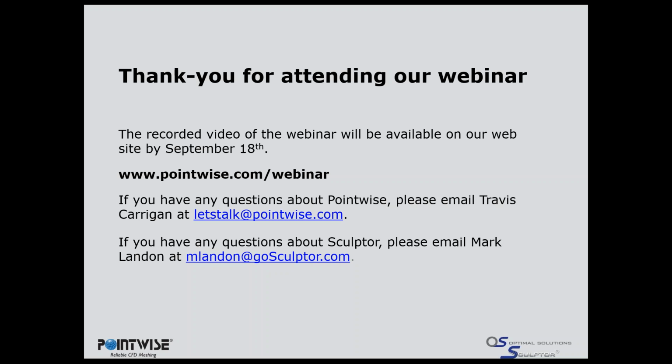Right, and the benefit there is that because we're using the same mesh and these changes are done locally, we're not really concerned anymore that the mesh is going to be influencing the solution in the way it would have had we had to remesh the entire thing from scratch. Because if we had to remesh it from scratch, now we're introducing an entirely new mesh to the solver, and we're not quite sure if the changes are coming from that or if they're actually coming from the parametric changes suggested by the optimizer. In this case, because we're deforming the exact same mesh and changes are done locally, it's kind of a best case scenario.